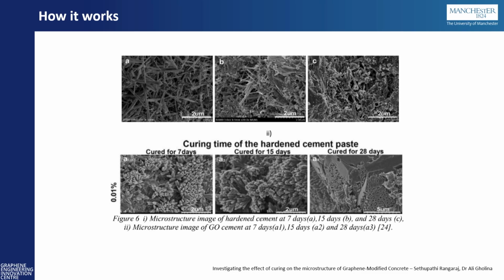What you get is this more regulated structure. And that's from that nucleation effect that you have during the cement hydration. The pore size is more regulated, it's more interlocking, and it's not more dense, it's just more regulated. People do say density, it doesn't quite work like that.